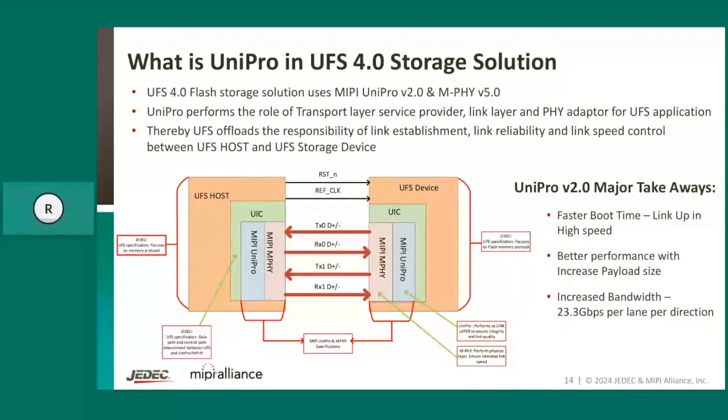Right. So here, just a block diagram as it shows, the UFS solution comprises 3 major specifications to establish chip-to-chip communication. The UFS layer has the UIC layer, which manages link layer and physical layer connectivity. Link layer and physical layer are nothing but MIPI standards. Those are UniPro and M-PHY. So in total, we see 3 protocols addressing the need of chip-to-chip communication in storage. Next slide, please.